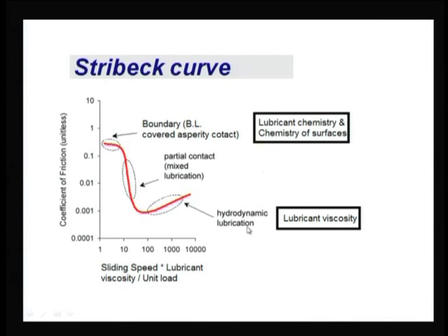And finally comes hydrodynamic lubrication, where the intermediate will be elasto-hydrodynamic lubrication, where basically the mechanism will be hydrodynamic lubrication, but along with that we will be considering elastic deformation of the surface and the viscosity thickening effect, which will increase the load carrying capacity. In fact, we say almost every element needs to have an elasto-hydrodynamic lubrication mechanism if we are really worried about the cost, if we are worried about optimum performance. Optimum performance happens at that point.